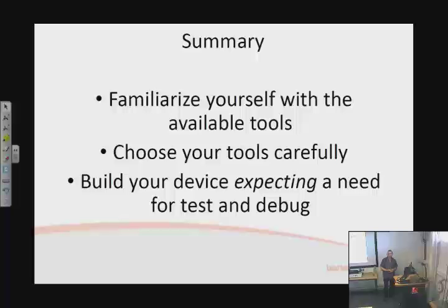Very useful indeed. And I think the main point though is that third bullet: when you design your equipment on the assumption that you'll be needing to connect test and debug equipment to it. And it's very easy to do if you think about it ahead of time. A few headers, a few LEDs, a few connectors here and there. You can always dispense with them in the second spin of your PCB, or just blank them out and leave them not fitted. But if you design them in from the ground up, it'll make your life a lot easier when you come to bring up the device.